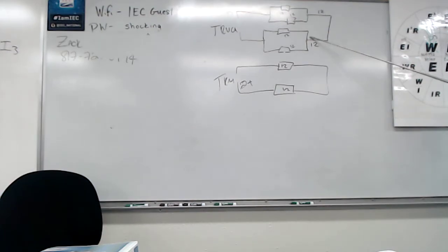Look at it. I'm doing exactly the way it is on here. But even though I hit this negative, I still got these two in parallel. This guy. Yeah, I get that. But for some reason, in my brain, those batteries would be adding. Yeah. They are adding. This set is adding to this set. But the top ones that you're saying are adding to the other one, those are parallel. But you also have the series that's connected. This set of parallel batteries is adding to this set of parallel batteries. We're only trying to get 48 volts. 24.